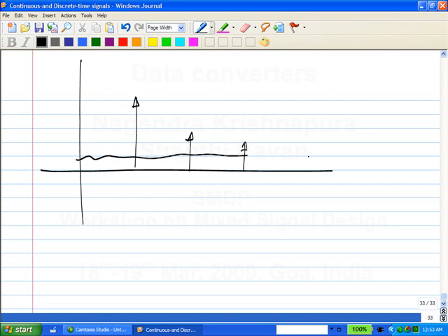The method of measurement is still the same. You apply a sinusoid so that its frequency is one of these good frequencies, and then you take the samples and you take the DFT. Let's say you take the DFT and you plot it. You can clearly identify the harmonics and non-harmonic components when you have chosen K to be odd. So that is basically how you measure it.